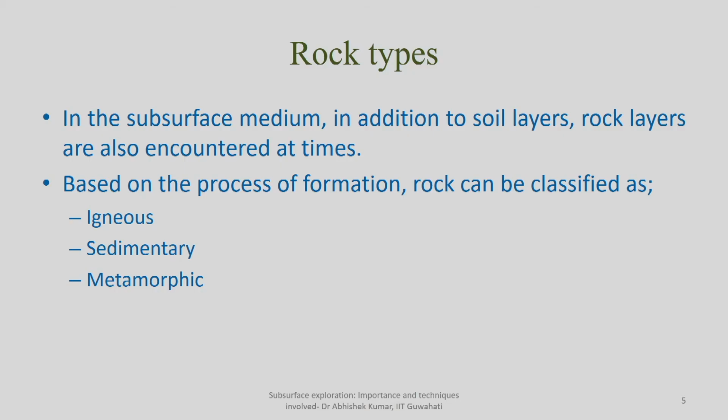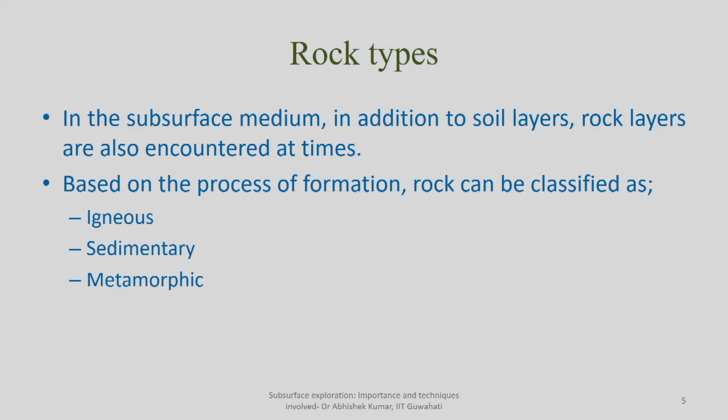It may be possible you may find some local boulders or gravel, you may find completely hard rock after 2 or 3 meters of soil, and you may find only rock available throughout the site of interest. So when you go for boring, you have to be aware of the ways of collecting samples from soil and the ways of collecting samples in rock, and how to examine those samples. In the subsurface medium, in addition to soil, you can have rock layers also, and how to deal with the rock layer is what we are going to discuss.